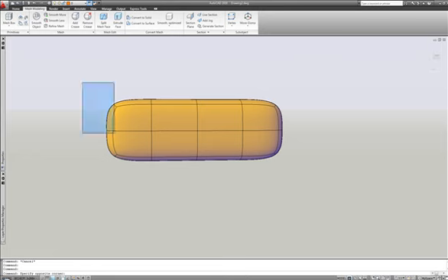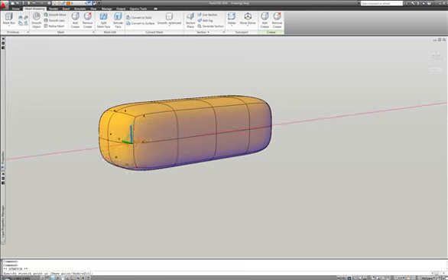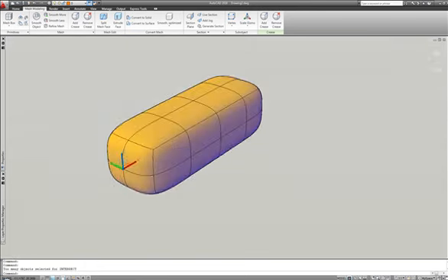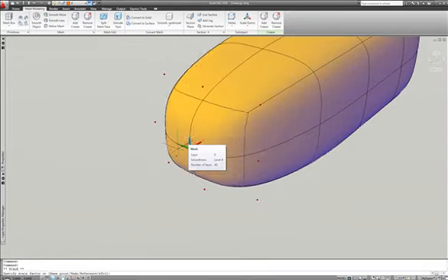Some other enhancements were also necessary, such as subobject filters and more functionality for direct manipulation of geometry with the gizmo. The user can work with different levels of smoothness and change them as appropriate. After smoothing the mesh, manipulation of the object is really easy with the new subobject filters, which allow the selection of different entities in the model.